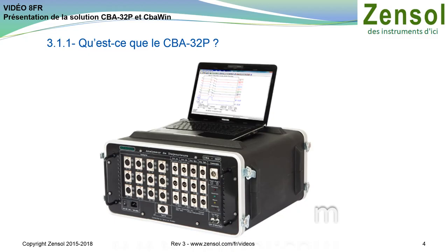The CBA-32P can record all kinds of events, fast or slow, thanks to its high sampling rate, ranging from 40 microseconds to 32 milliseconds, and exceptional recording times ranging from a few milliseconds to 17 minutes. It's the flexibility of these 2 parameters that has made the CBA-32P such a success over the years. Finally, the most popular 24-contact model can record up to 38 signals simultaneously, including 24 digital dry contacts, 8 analog signals, and 6 optical encoders.